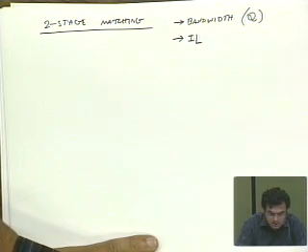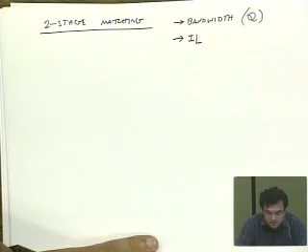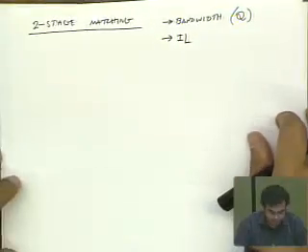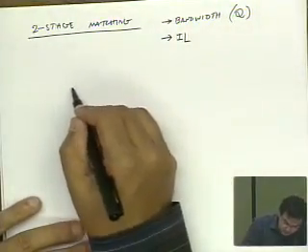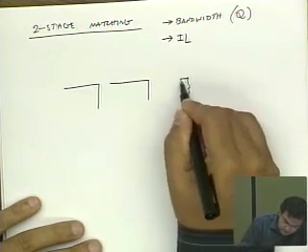The reason is that insertion loss is really related to the network quality factor. And in certain circuits that have extremely high network quality factors, using multiple stages can actually relax the quality factor. We'll see how that works out in a moment. Let's talk about two back-to-back L sections. So let's say that I have two L matching networks like this.